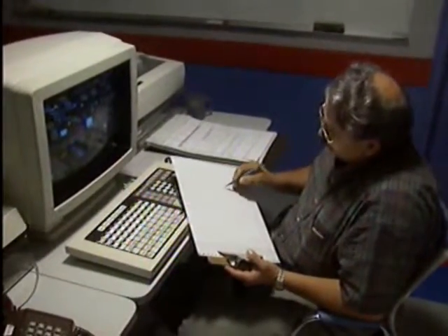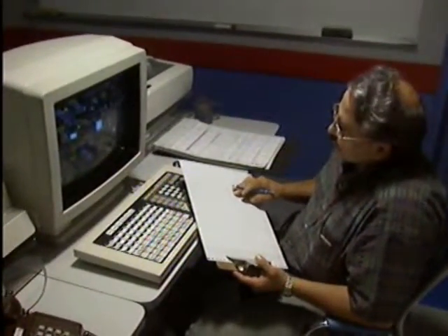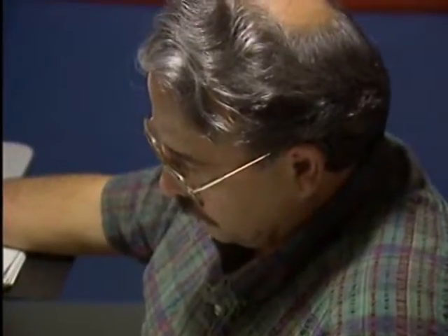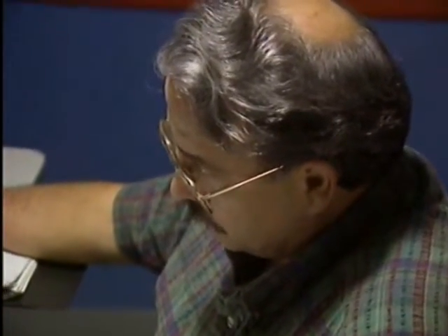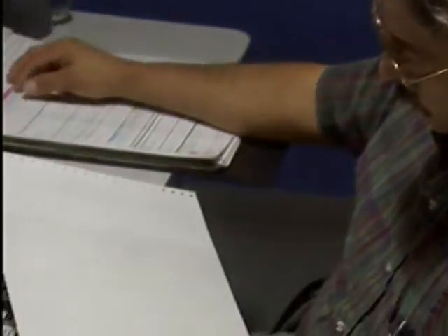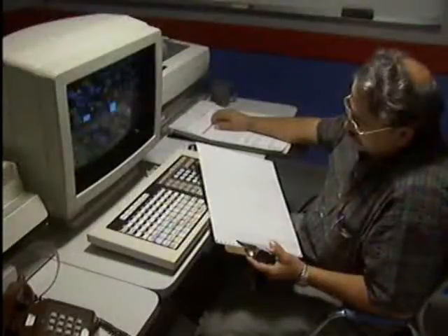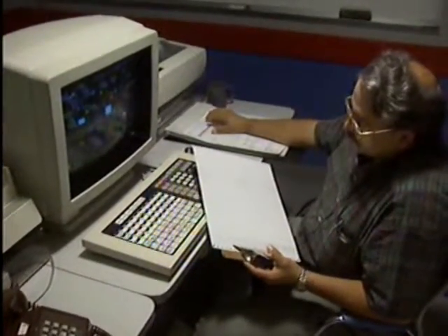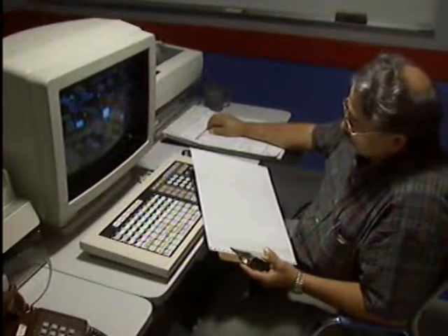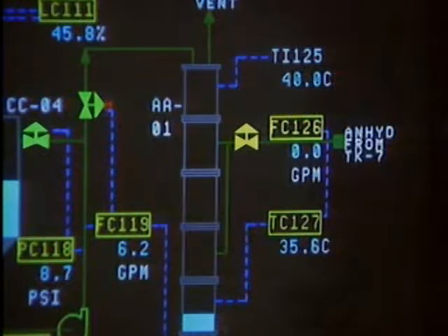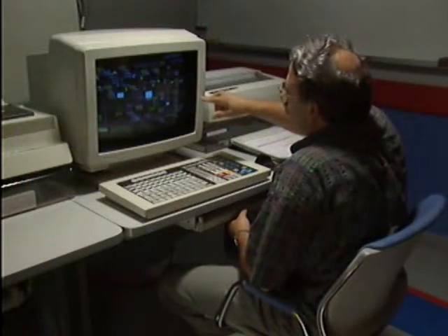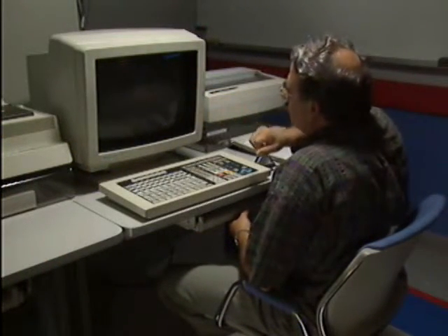The operator has already tested the composition of the materials leaving the column. The control room operator can compare those results to test results on the composition of the feed material. The composition of the feed material dictates what the final product should be. After comparing the compositions, the control room operator decides that the column is properly separating the feed material into the desired final products. The operator's next step is to check the flow rates entering and leaving.